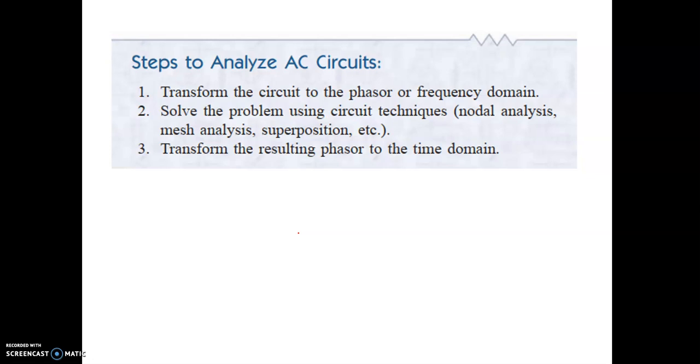After that, we have to solve our problem using various techniques. It may be nodal analysis, mesh analysis, superposition theorem, or any other theorems. Finally, the result should be again converted from phasor quantity to time domain quantity. So these three steps need to be memorized for solving any problem in AC circuits.